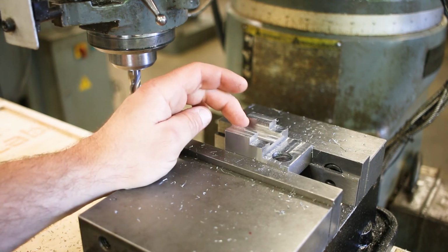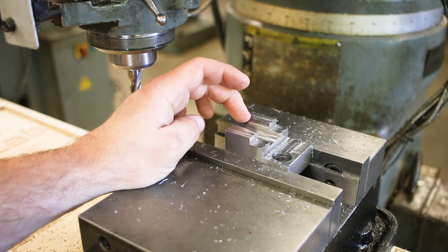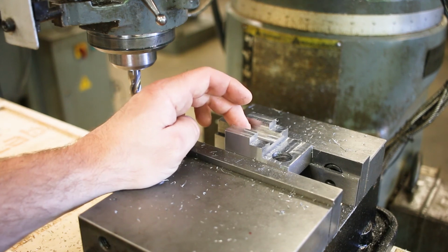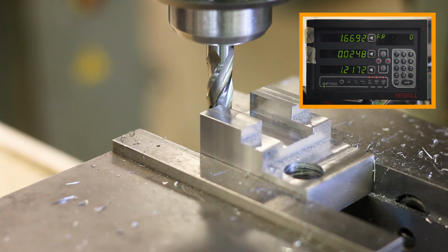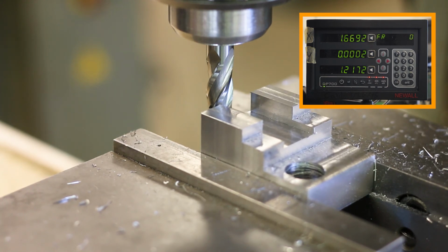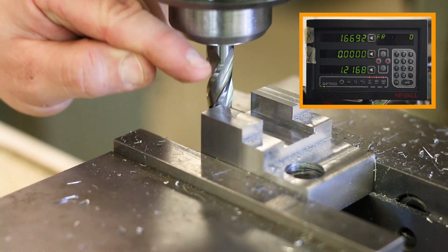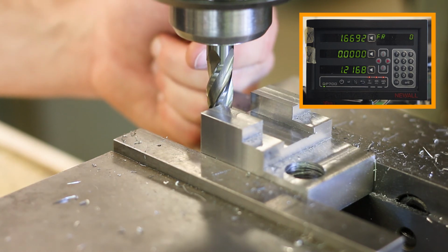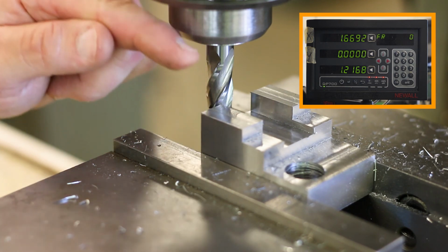But just so that we can go through the exercise so that you can see what you would need to do if you were dramatically offset from the center position and you really needed to adjust this, I'm going to go ahead and adjust the center position to really dial this in. Okay, let me go ahead and move this back to the 0 position. Right there. Okay, so this is the tab, which is 1 thousandth of an inch wider than this one. So we need to adjust the 0 on the digital readout so that we bring the end mill closer to this tab, so it takes more material off of here.